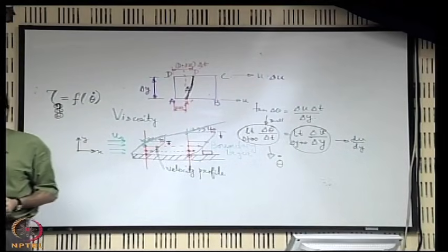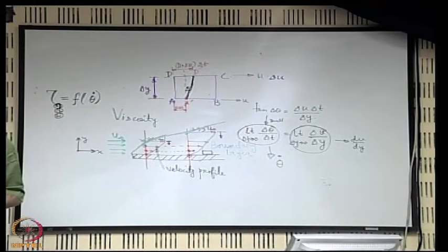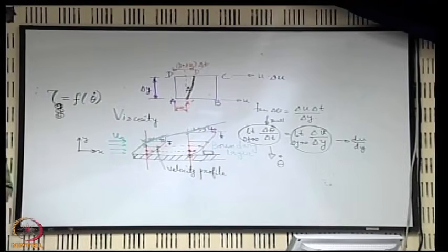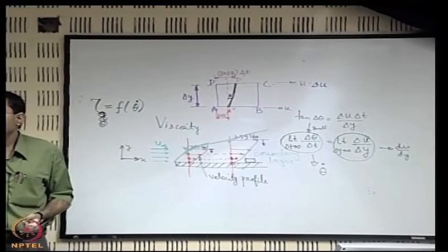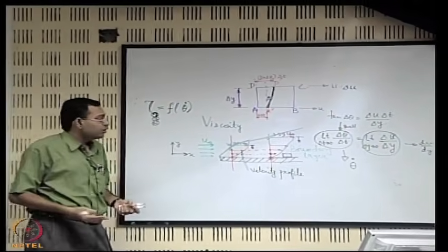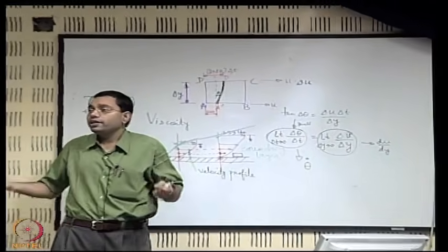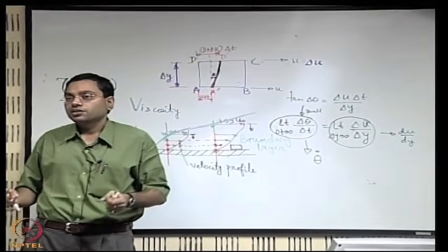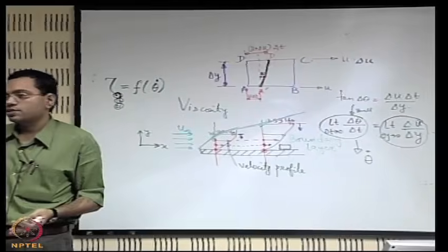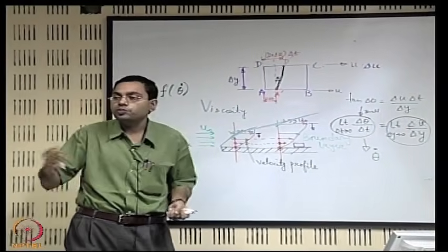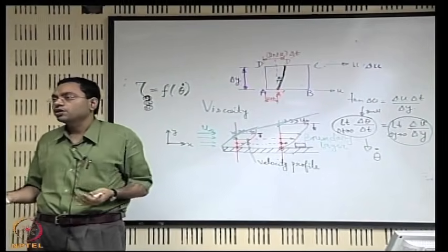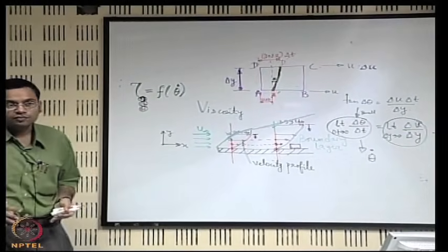But if you have an elastic material, then within the proportional limit stress is proportional to strain, and that proportionality is connected with an equality through a material property known as modulus of elasticity. Of course, all materials are not linear elastic materials, but this particular law, Hooke's law, is a very popular one because many engineering materials obey that behavior within proportional limits, and many times in engineering we are working within those limits.